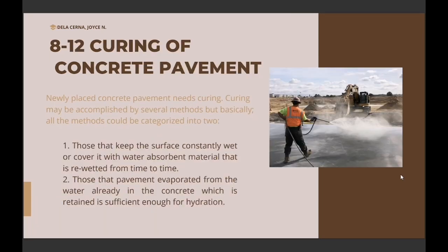Curing of concrete pavement. Newly placed concrete pavements need curing. Curing may be accomplished by several methods, but basically all the methods could be categorized into two. Number one is those that keep the surface constantly wet or cover it with water absorbent material that is re-wetted from time to time.